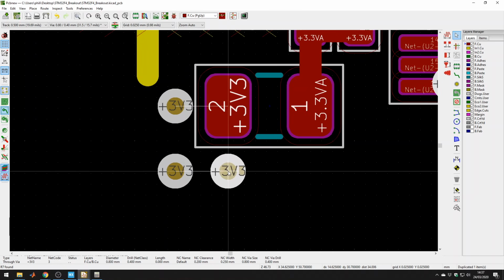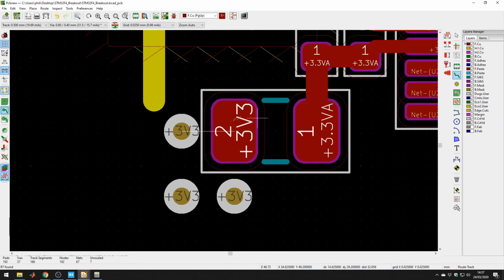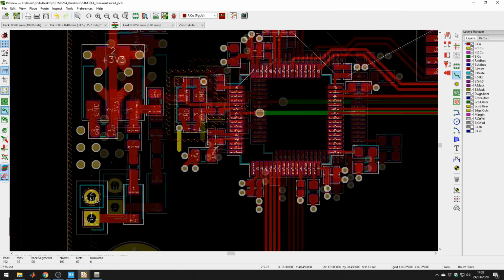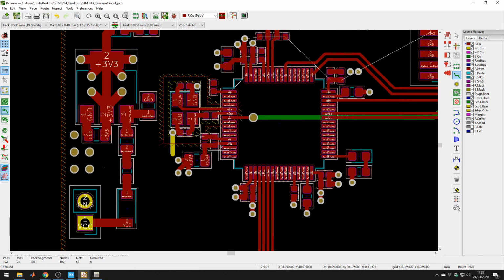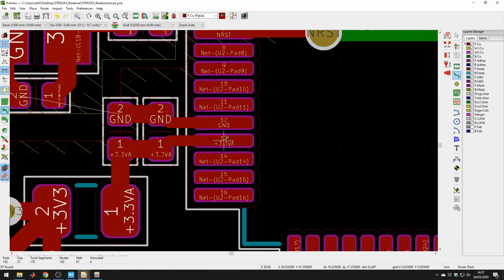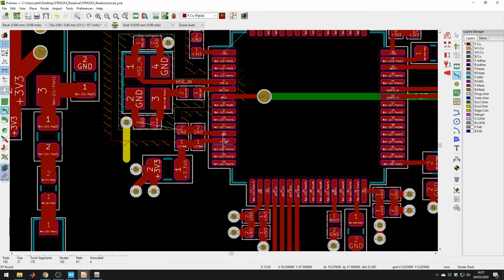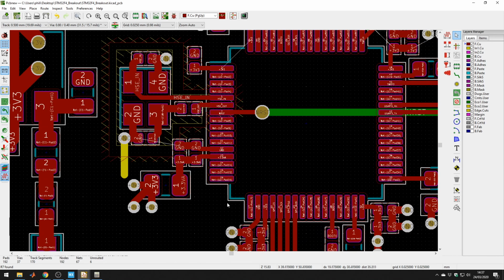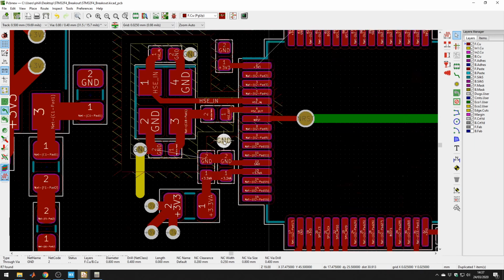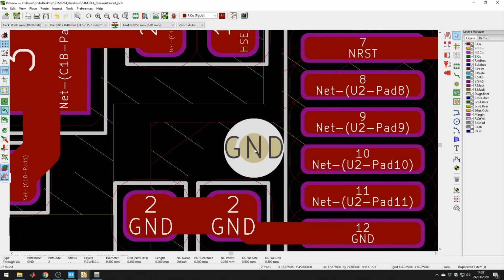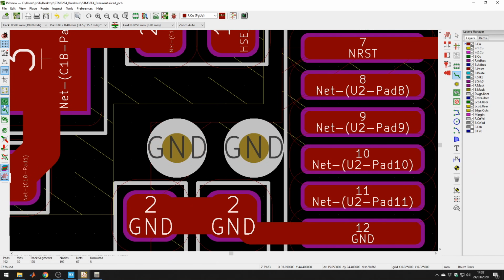Okay, for this one I'm adding quite a few more vias because this is the analog reference. Of course here we're not using the ADCs or DACs or anything, so in essence this analog voltage pin is a bit useless in this circuit, but nevertheless. Here it's a bit fidgety because we have to stay on the ground pole.